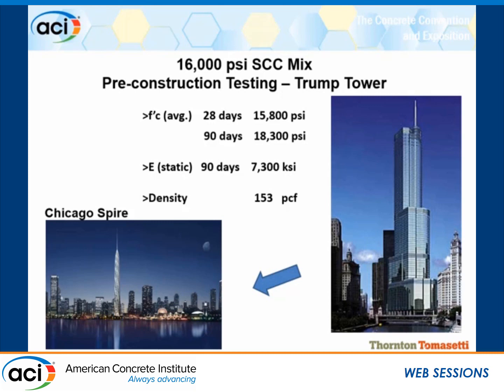And the reason that's important, at least in Chicago, is there's a history of taking concrete one step at a time, project by project. So if we can use the technology for a project, do some testing, pour a column or two with high strength concrete, and then use it on the next project as a test, that's what the industry should be doing, rather than starting from scratch all the time.